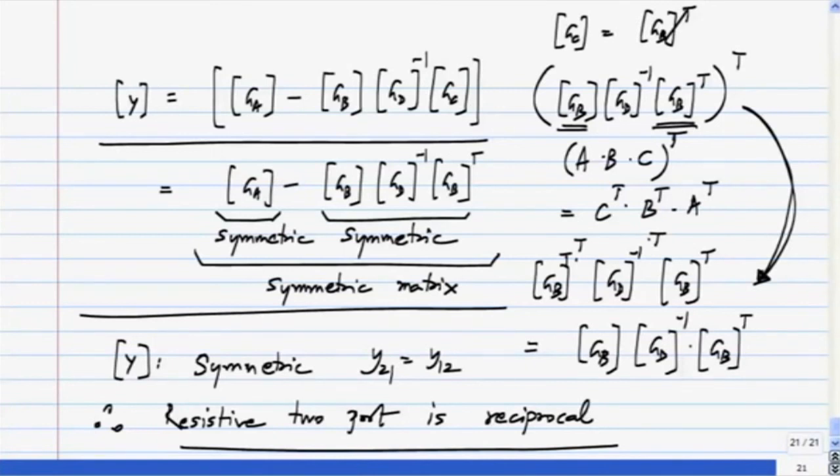So instead of starting from Tellegen's theorem and getting these results, we could also do it by defining a two port with some two port parameters. We try to calculate the two port parameters from basic circuit analysis, in this case nodal analysis, and you can find that the Y matrix happens to be symmetrical. Of course, if you find any one parameter set to be symmetrical, the rest of them follow the same symmetry. Now the Z matrix will also be symmetrical, and if you look at G or H parameters, G12 will be minus G21 or H12 will be minus H21 and so on. So this is an alternative proof of reciprocity in resistive two port networks.